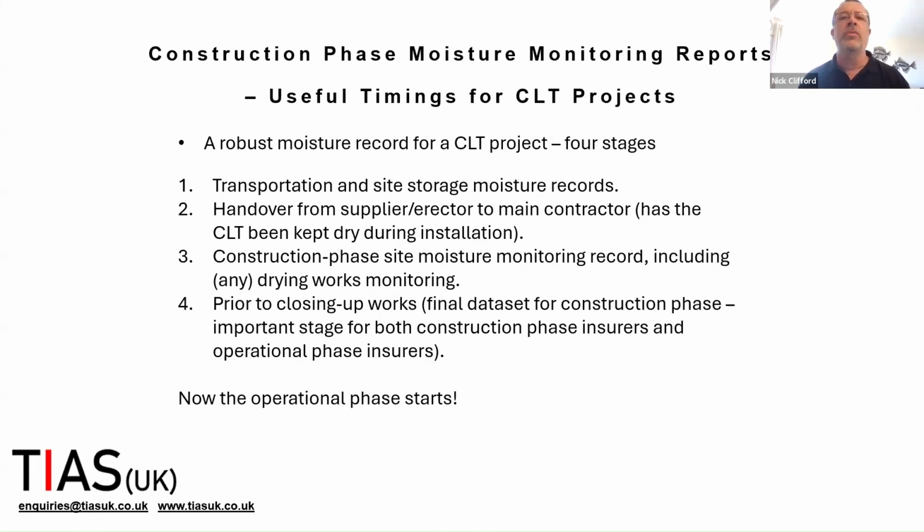And then the really key data point for moisture monitoring is on the closing up works. It's kind of like a final data set for the construction phase. And if you can show that that building is dry on closing up, that's important for you as a contractor because you've shown that you've delivered a dry building. And that's going to be important for your insurer. And also additionally for the operational phase, it's a starting point. It's a fresh slate for the operation phase of the building.